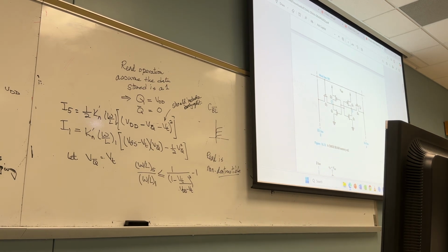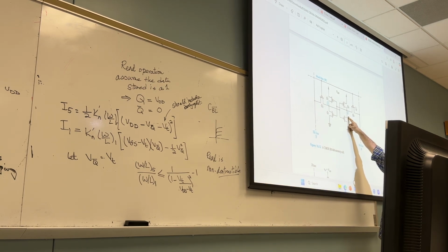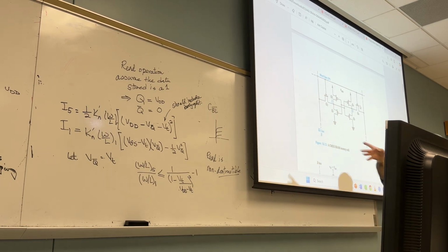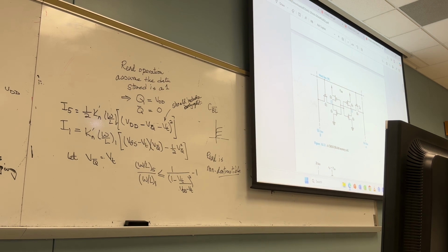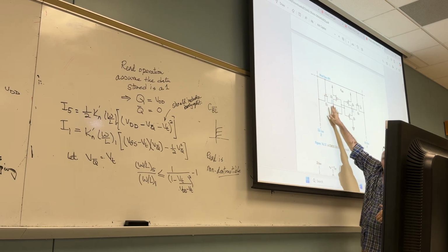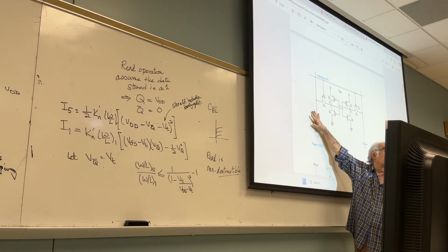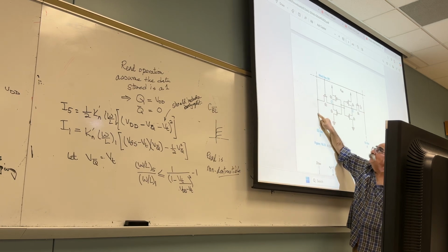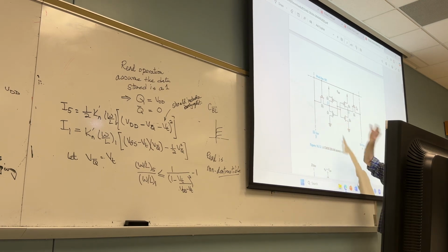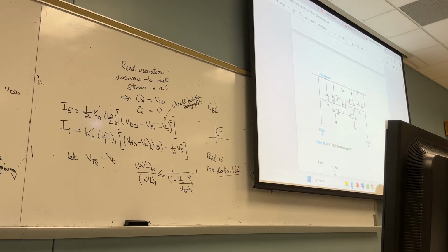Can you tell me the procedure? Exactly the same thing. In other words, this Q is 0. Q bar is 1. Can you give me the procedure? Exactly the same as this one. Pre-charge to VDD, both. This side does not conduct. Why? That's a 1. VDD, VDD. If we assume Q is 0, are you following me or not?